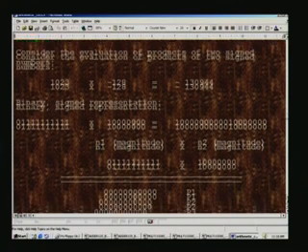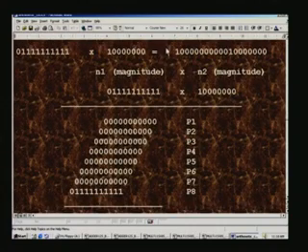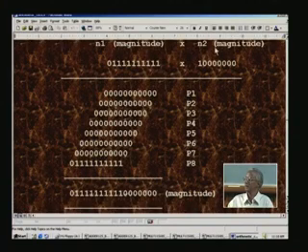As mentioned before, we will take only the sign of these numbers, and which is this here. This happens to be exactly the same, and for 128 minus and plus happens to be the same, and this being a positive number, automatically the same number is put here for magnitude. So we can evaluate magnitude merely by taking 2's complement of any number. For example, if you take a 2's complement of this, out comes the magnitude of this number, and we can identify this number as a negative number by inspecting the MSB, which happens to be 1.